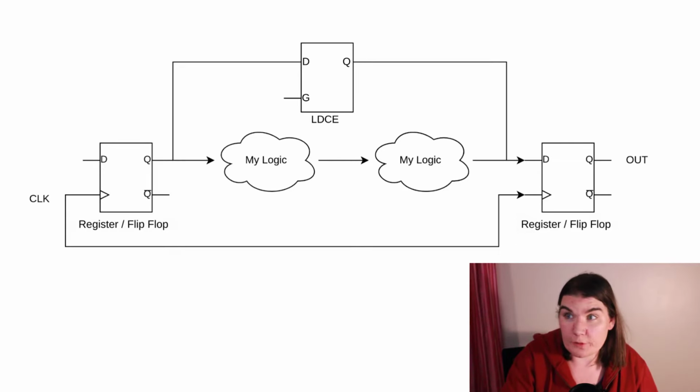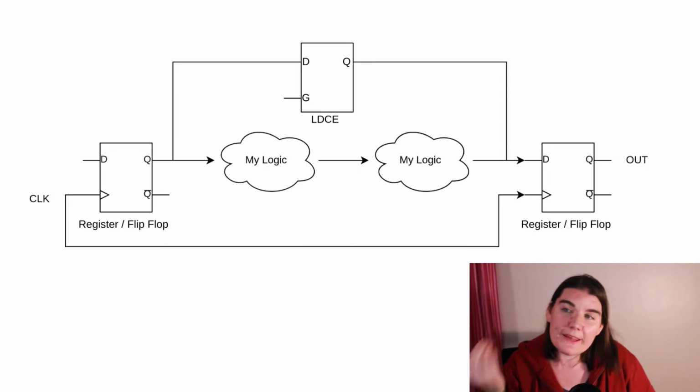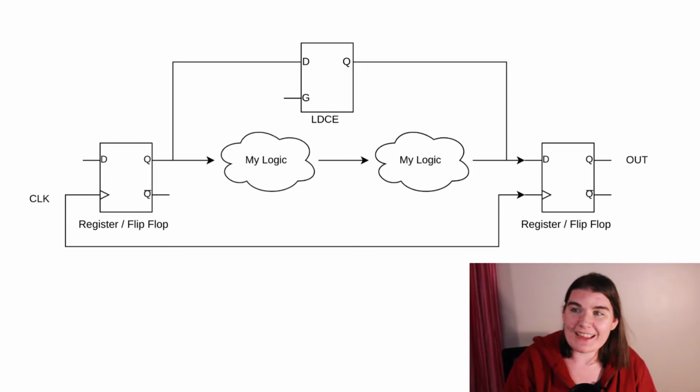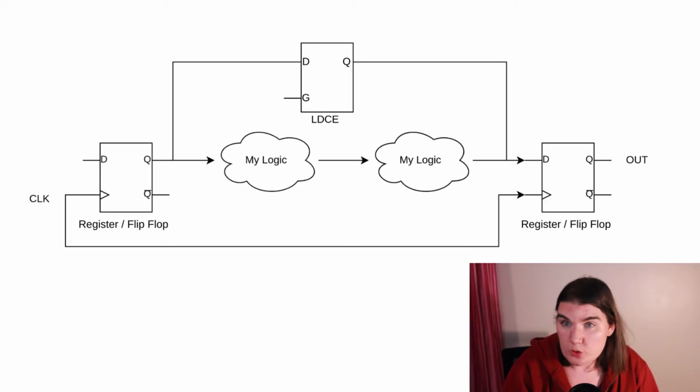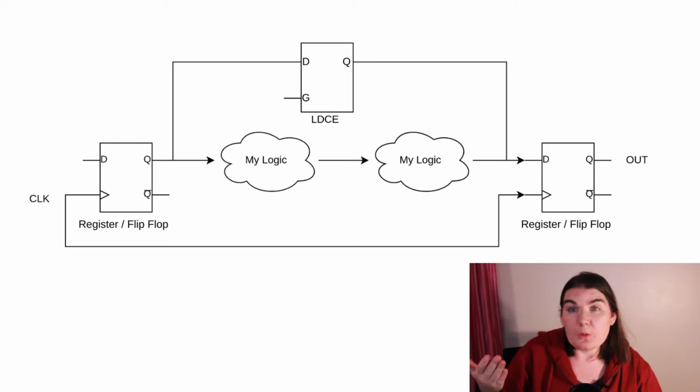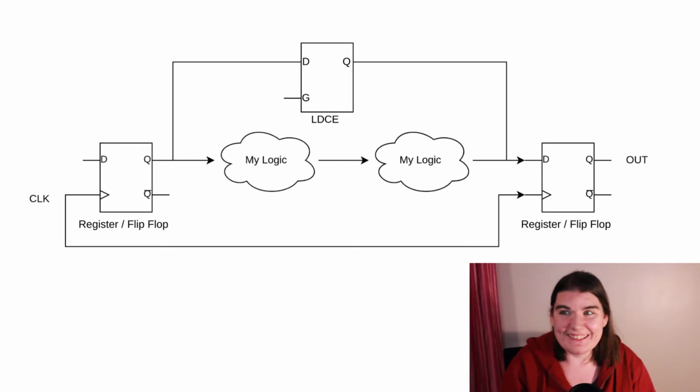This is called an inferred latch. And so when we are inferring a latch, we are putting a hacky memory element. The tool is automatically putting a hacky memory element inside of a loopback path inside the FPGA. That is what's happening. So anytime you have a loopback in asynchronous logic, the tool is going to need to infer a latch. And that is why we say that you mustn't do that. We highly recommend not putting loopbacks in asynchronous logic.